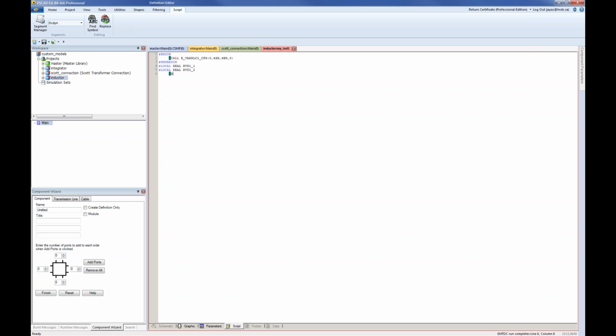So the first variable is the resistance created by the inductance in our representation, which, if you remember the previous slide, is 2L over delta T. And the second signal is the value of the voltage source. There's the branch current times my resistance plus the voltage across the branch.